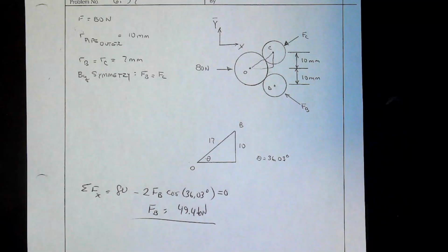Our next problem. So, we have an engine here, which we're told is 125 kilograms. And the question for this problem is find the load in members DB and FB. So here's DB and here's FB. We're asked to find the load in this hydraulic support and in this two-force member. The hydraulic support will obviously also act as a two-force member, just force along the connections here. Okay?